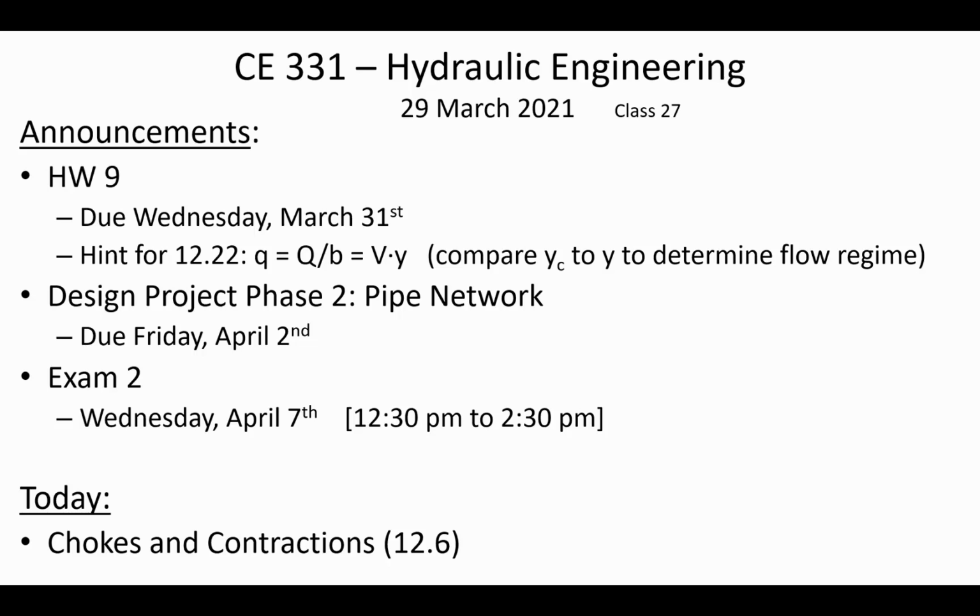But the annotation is the important thing, so that I can see when you turn in the maps what's the diameter of the pipe, what's the length of the pipe, what's the elevation of the junction, how much flow is coming out of the junction, what's the pressure at each junction. With the annotations, then that'll help me to know how close to the edge you're getting on this design.